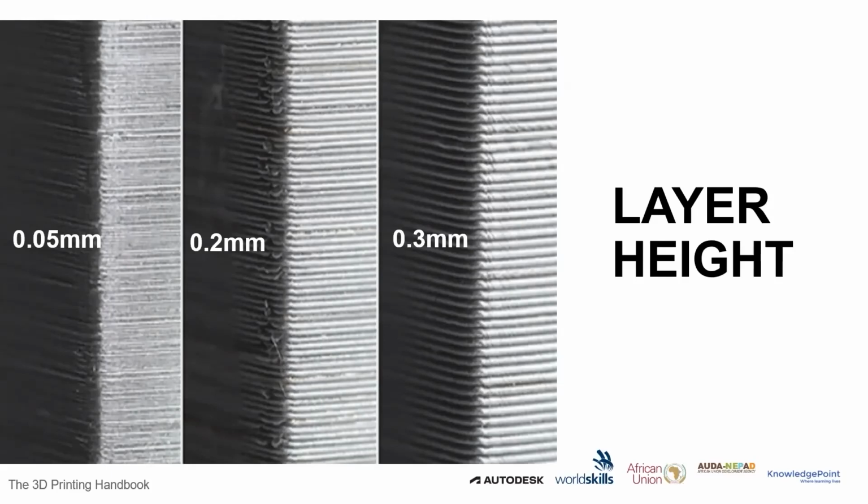So why does it really affect the printing time? First, your slicer slices each level of the layer height. So let's say you sliced with 0.2 and it gave you about 100 layers, and then you slice with 0.1, it means that you're going to be doubled. It means your printer will go through different Z axes positions as you keep moving up and up.